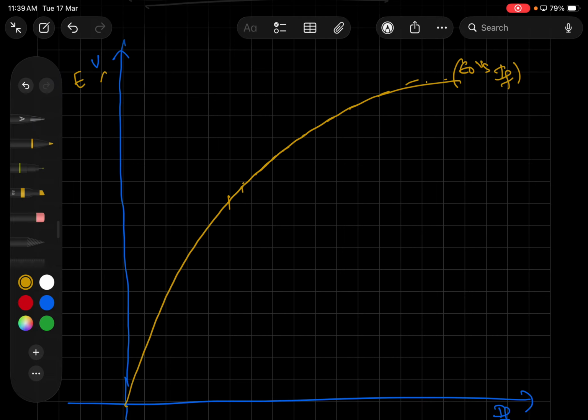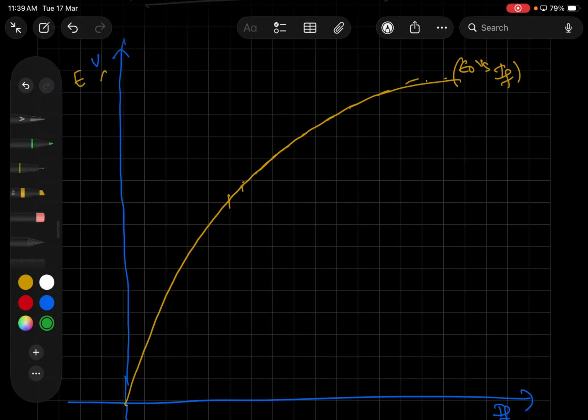The air gap line indicates that if there is no saturation, the ideal characteristics would be the air gap line characteristics. This is normally represented as the AG line, which represents the air gap line. So I need to draw the air gap line approximately.